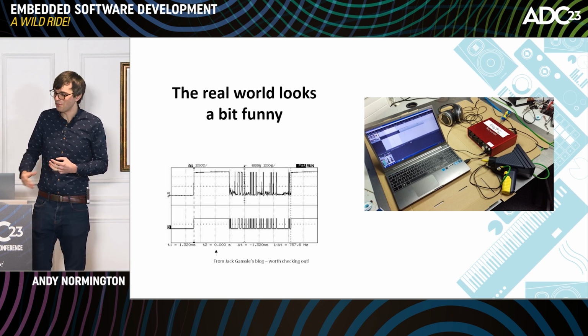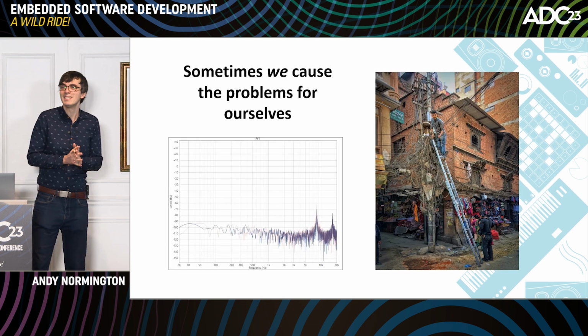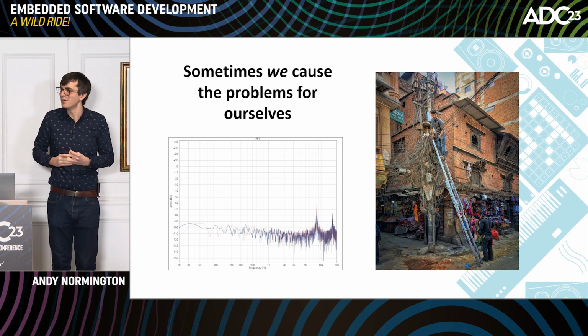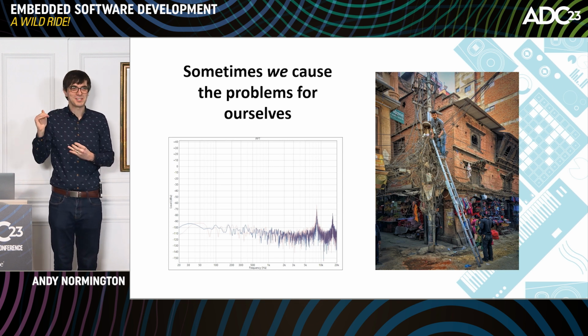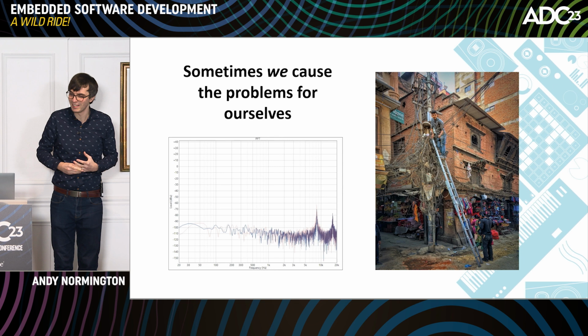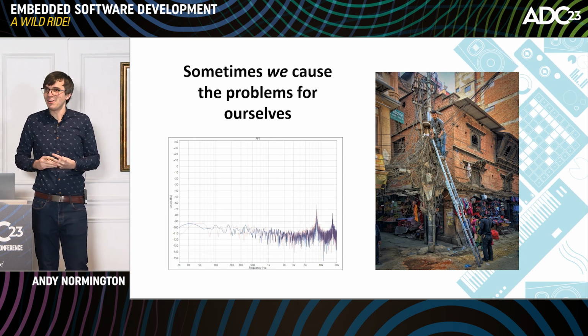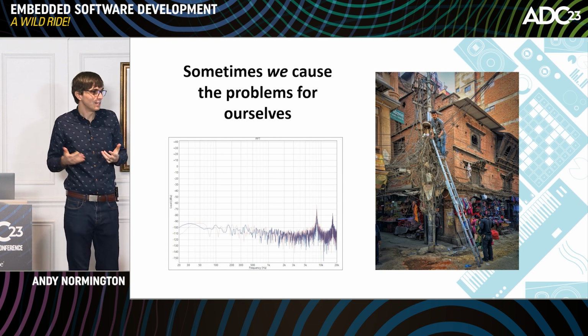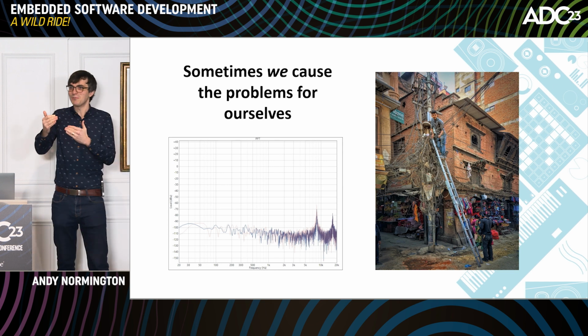The microcontroller itself can also be a noise source in the rest of the system. Every time we're crunching numbers, we're doing some work, we're pulling a little bit more current and causing a small voltage fluctuation on the power and ground rails around the microcontroller. If we've got periodic work to do, say in synchronization with the USB frame rate on our audio interfaces, we've got a chunk of work to do.